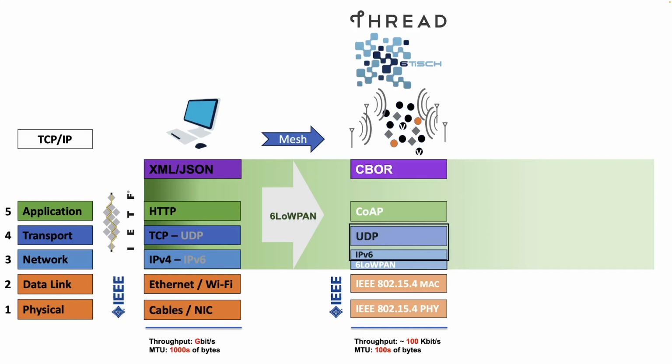Finally, on top of the CoAP, there is CBOR, which is a binary data serialization format loosely based on JSON. CBOR stands for concise binary object representation. In the near future, we do plan to have a dedicated video on CBOR, so please stay tuned. Now, combining the CBOR, CoAP and 6LoWPAN protocols, we can get overheads down to just tens of bytes, which can be carried in constrained mesh technologies such as Thread and 6TiSCH that come with MTU of 127 bytes.